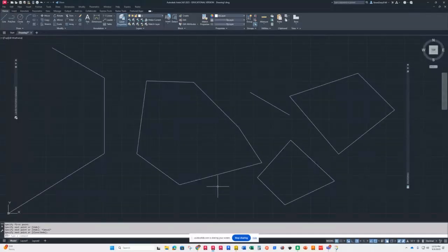Now, like I said, on polyline, close is a good thing to do because if you were to go in and edit it, so to edit a polyline, use what we call p-edit. So I'm just going to go ahead and show you an editing command while we're at it. So maybe we'll just show you the draw and the edit at the same time. So p-edit, or polyline edit, you select the polyline you want to edit, and then what if you wanted to go with the width?